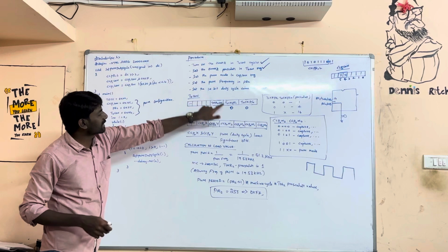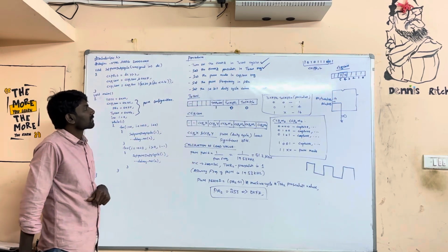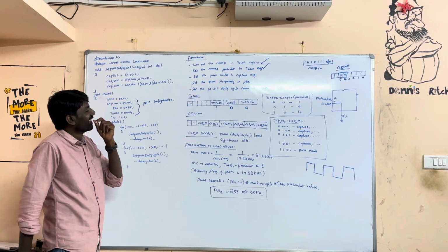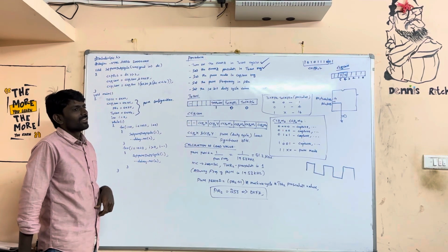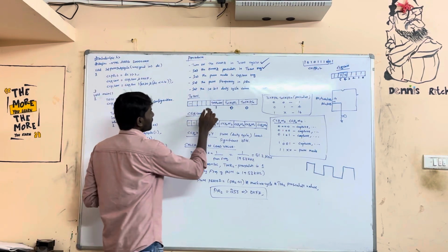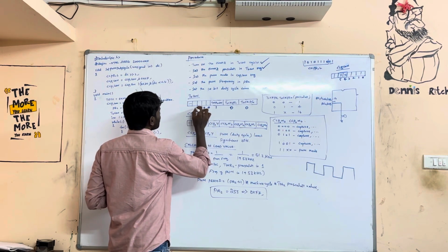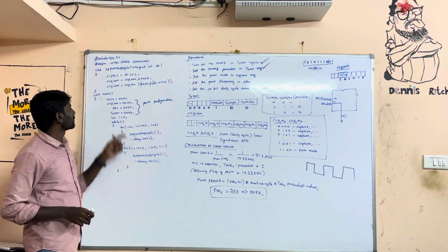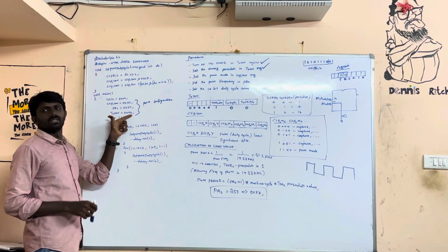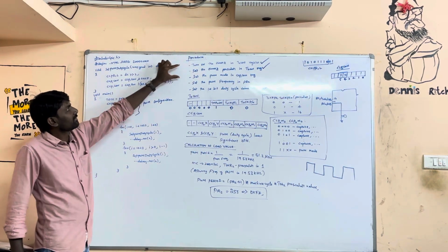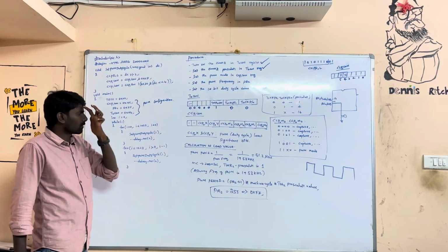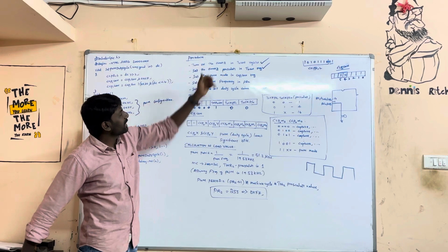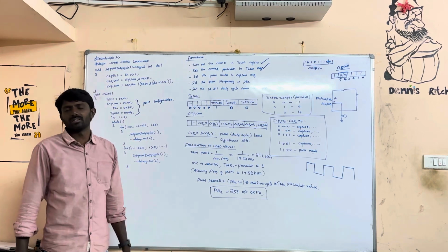So now what is the hexadecimal value? 0x40. Okay, so this all should be 0. 0x04. Got it, right? So T2CON is 0x04. So we are done with the first 2 configurations. And coming to next, set the PWM mode in the CCP1CON register.